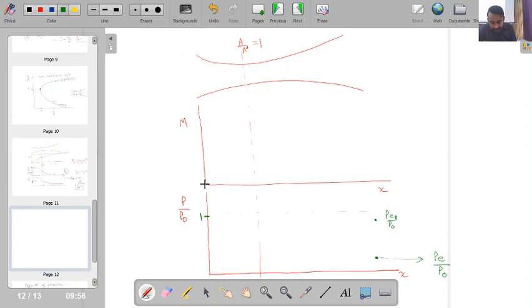So from Mach equal to 0 my flow has started, but the flow rate was so small that I am not able to reach the Mach number of 1. I am reaching a Mach number which is much less than 1 at the throat. If my Mach number is less than 1 at the throat, then further downstream I am having an increased area, so this is becoming a subsonic situation, and I will be having a further decrease in the Mach number.